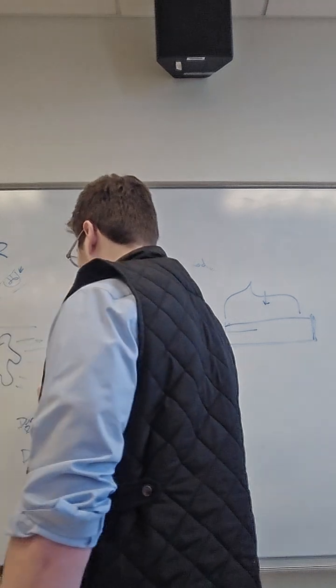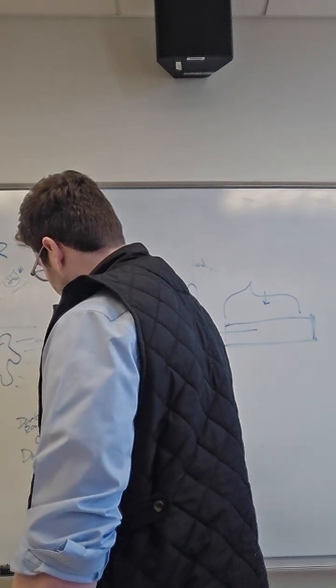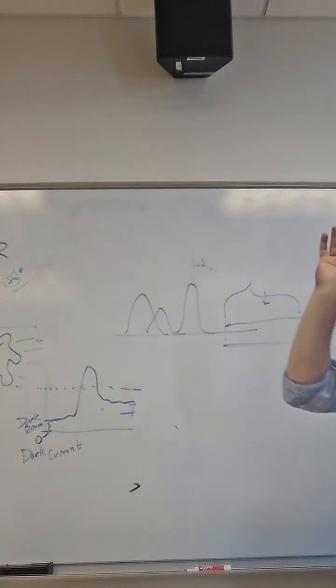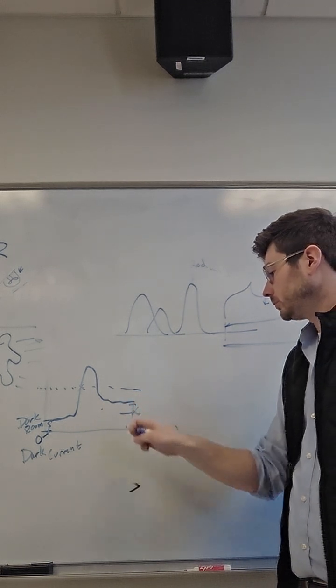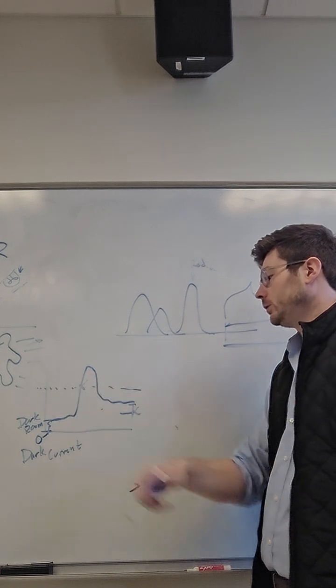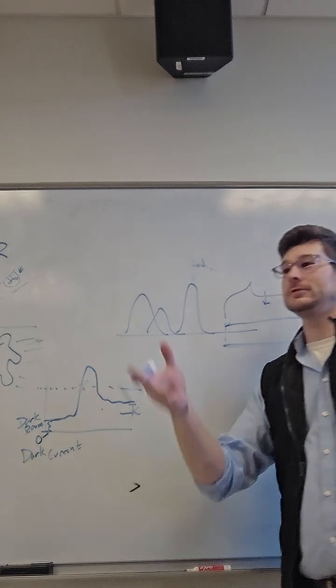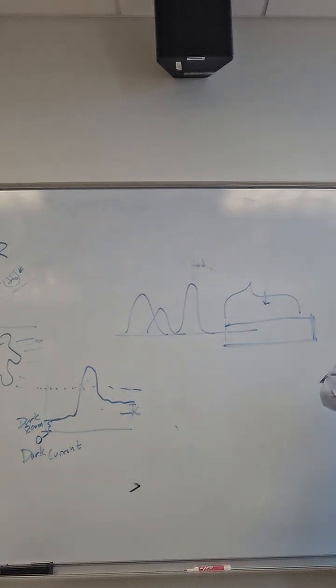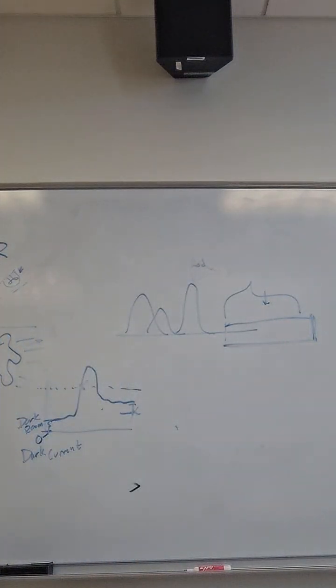So we would do something where we either set a trigger where we look for this high point, right, for it to cross that threshold right there and then turn on the light. And then as long as we are above our dark room currents, we keep the light on, right? Or maybe we always look for this and we just keep it on for an hour and then we wait to get triggered again. And then if we get triggered again, we keep the lights on. If not, we turn the lights off, however you want. But that is a very common example of PIR.